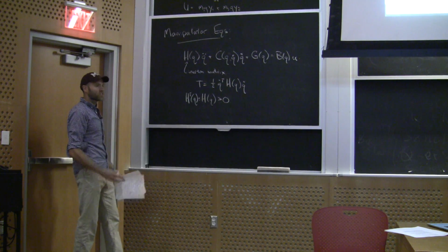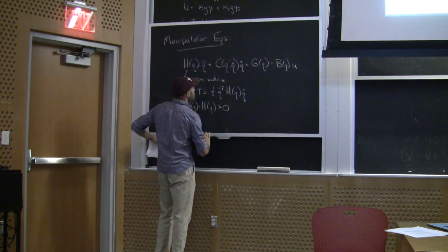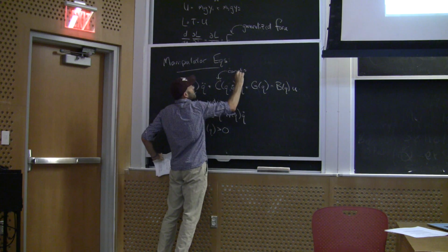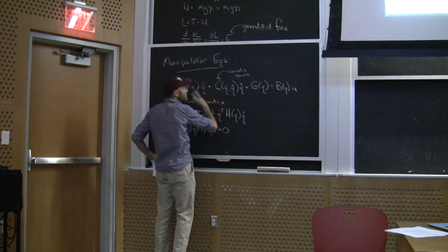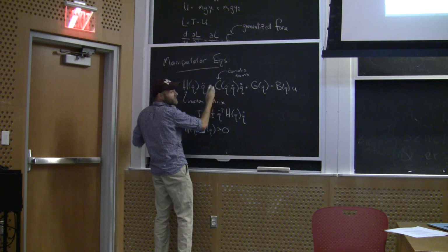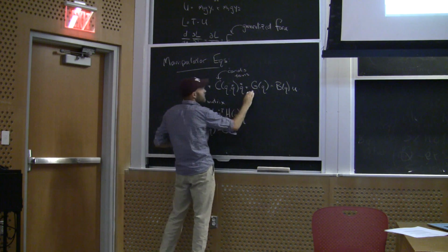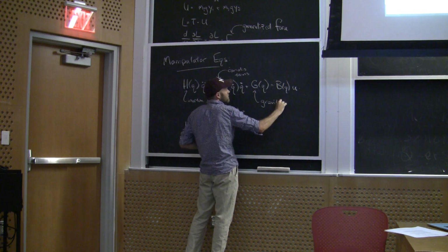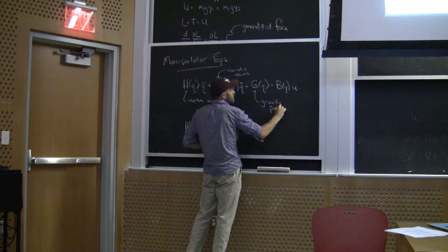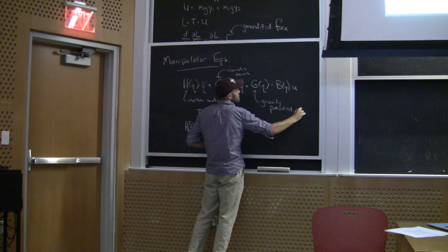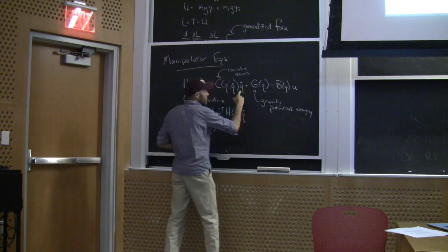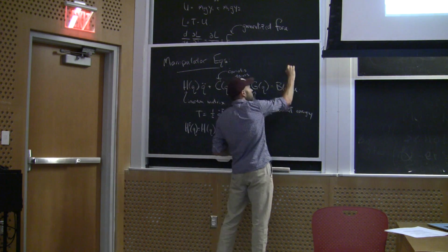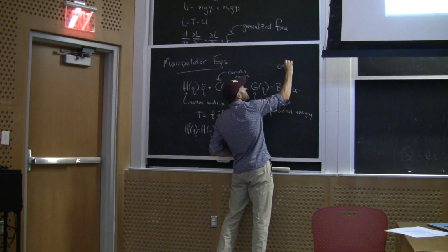Okay? And it's just gobs of structure in these equations. This is the Coriolis terms, roughly speaking. It has structure, you know, H minus 2C is skew symmetric. There's all kinds of structure like this. This is roughly the potential, the gravity terms, that's why it's got a G. Terms from potential energy. These Coriolis terms always have a component in q dot, and it's control affine.